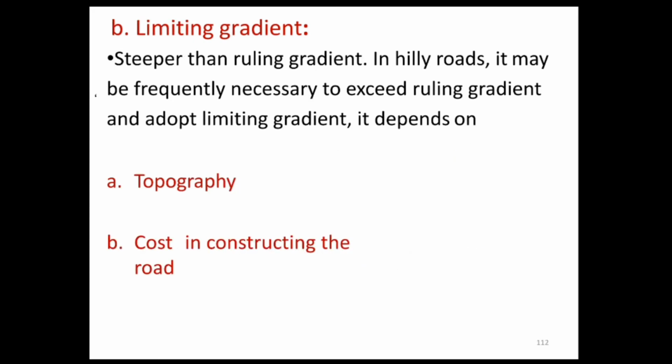So wherever the topography of the place compels adopting steeper gradients than ruling gradients, limiting gradients are used in view of the enormous increase in the cost of construction of roads.